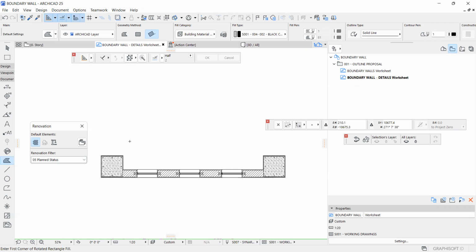When you are drafting, especially when you're doing it manually, you must learn to project. And in our case, when we're doing an orthographic projection, we'll have the plan, the top view, we'll have the front view, we'll have the side view or side views, okay? So I want to quickly do an orthographic drawing for this. Again, just learning the basic concepts. By the time you go to modeling, most of these things will be automated. However, it's important that you have control of what is being automated. Because if you don't know how they are done, at the end of the day, you will not be sure whether whatever you're doing is correct.